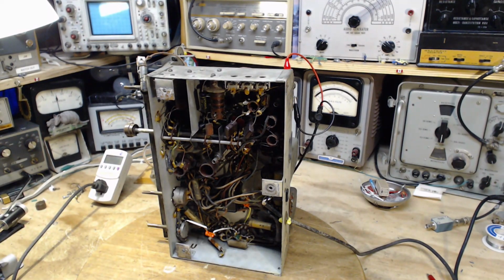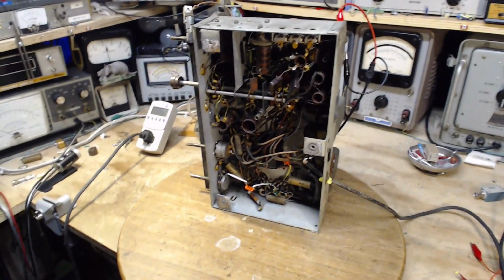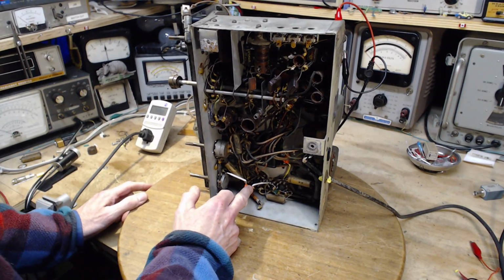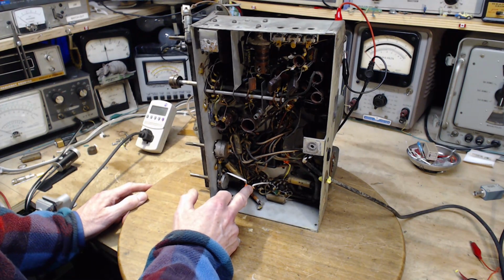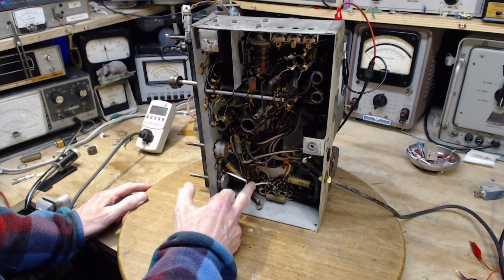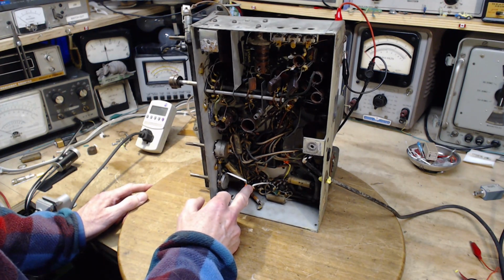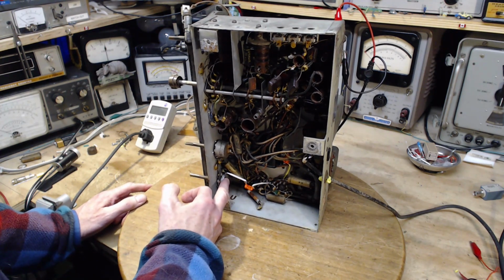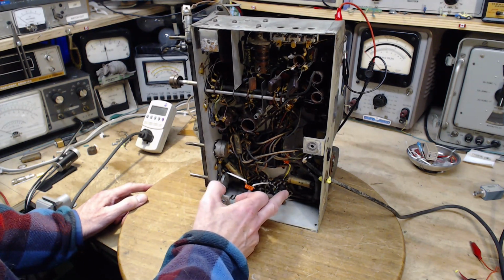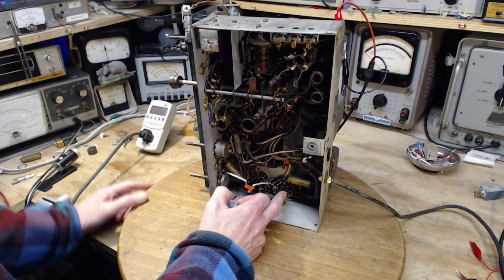Now, yesterday, in the last video, I replaced the capacitor that's here now, and in the course of doing that I operated the radio briefly without any connection here, without any capacitor here at all. So this is the volume control, and the output from the volume control goes through this capacitor on its way over to the amplifier over here and eventually out of the speaker.